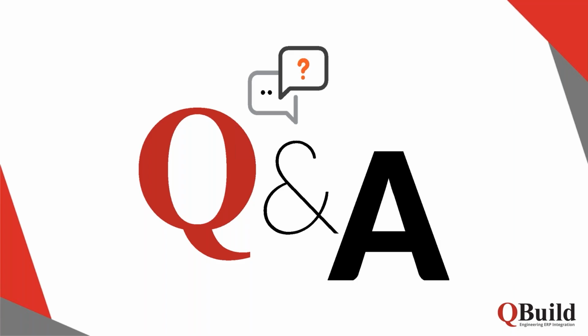Another question here: how does CADLink know the field mapping between the CAD system and Fourth Shift? Good question. That is actually configurable by the user in the CADLink settings. So I, as the user, have the ability to tell CADLink where the item number should be coming from in my CAD system, as well as descriptions, quantities, etc. That's all configurable in the CADLink settings.